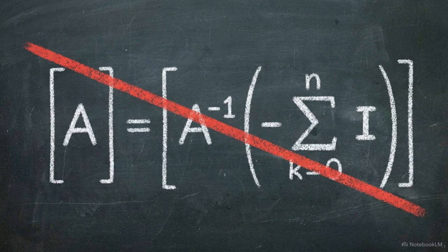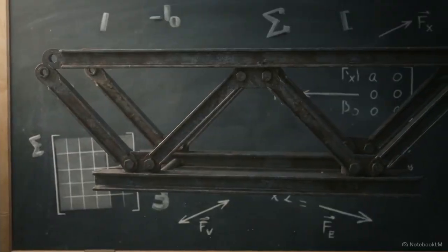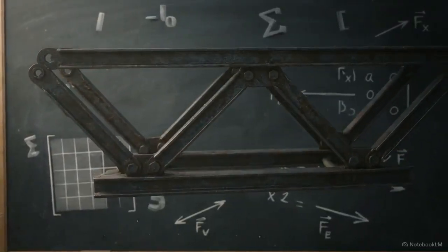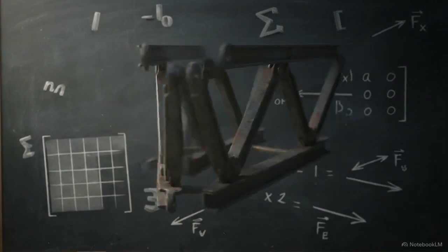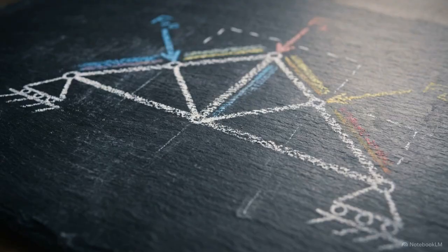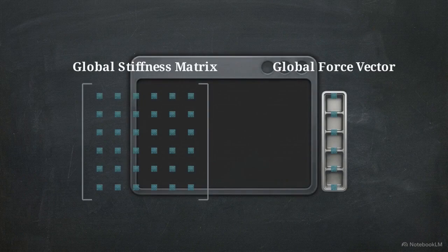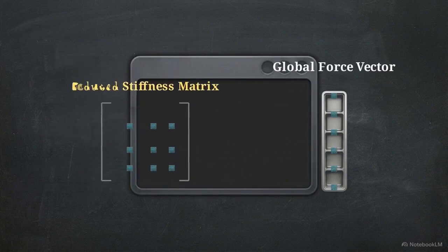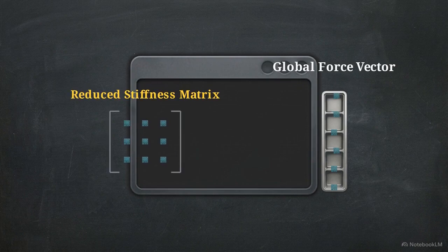At this stage, the global stiffness matrix is singular, making it impossible to solve directly. Physically, this is because the truss is not yet anchored. Without constraints, the math allows it to move infinitely through space. To fix the structure in place, the program identifies the degrees of freedom at the support nodes that are prevented from moving. We enforce these constraints by removing the rows and columns associated with those fixed degrees of freedom. This smaller, dense block is the reduced stiffness matrix.